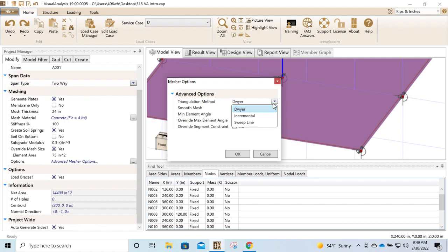Because in reality, we're all looking for a certain result for a certain design. As I mentioned, if I was designing the frame members, the beams and columns in that frame, assuming that the base plate was fixed, I'd just fix the node and move forward, right? But if I was looking at soil interaction and I wanted to know how the overturning of that frame is going to affect the footing, then I would want to incorporate the footing, and the stiffness of the soil underneath that footing.